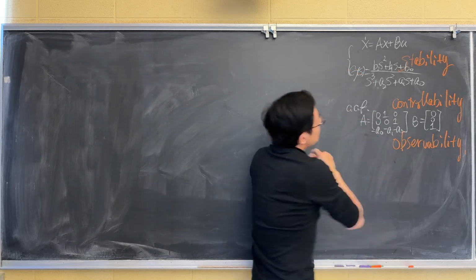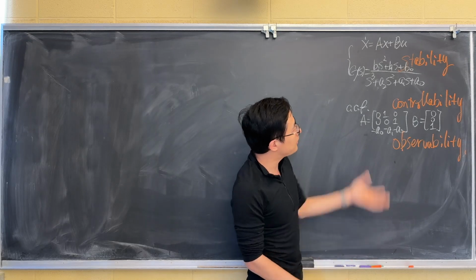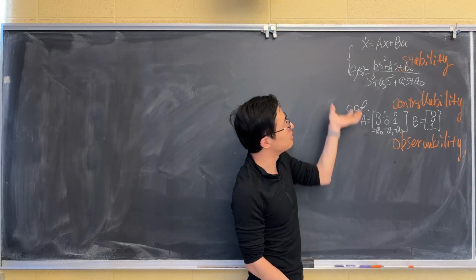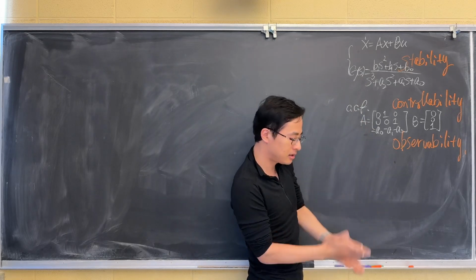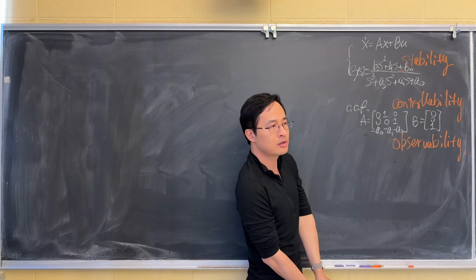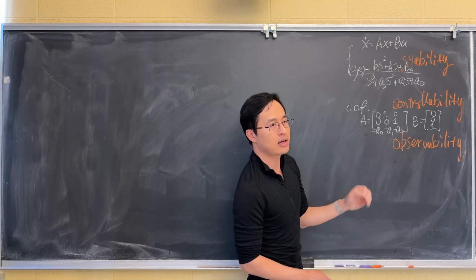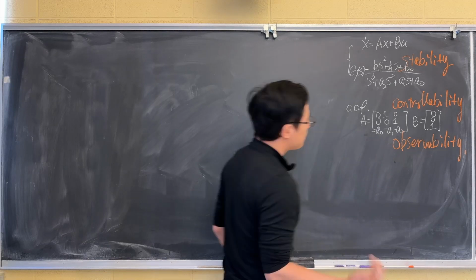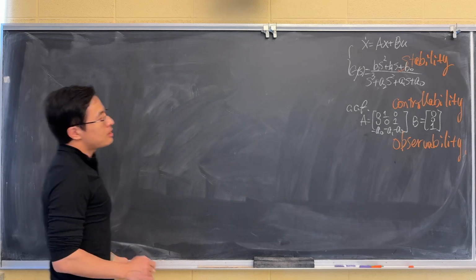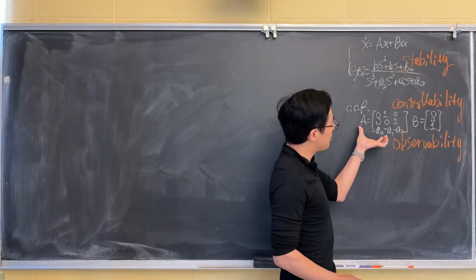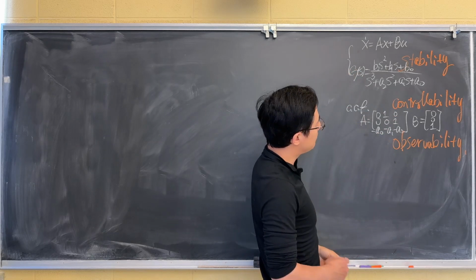Then it is immediately relevant to ask: if a system is not stable but controllable, how can I make it stable? What's the degree of freedom I can use to do that job? How freely can I stabilize the system? That's the topic for state feedback control. Let's start with a 3x3 simple case. The system is third order. We have the transfer function. We have the system A, B matrices.